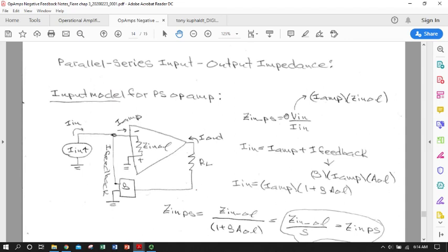We're going to apply Ohm's law. We're going to say that is V at the input terminal right here, coming out of our current source, whatever that voltage is, divided by the total current we're putting in. So R equals V over I. But we can define Vin in terms of this input resistor. If I look at the top of this, there's no other resistances, no other opportunities for voltage drop.